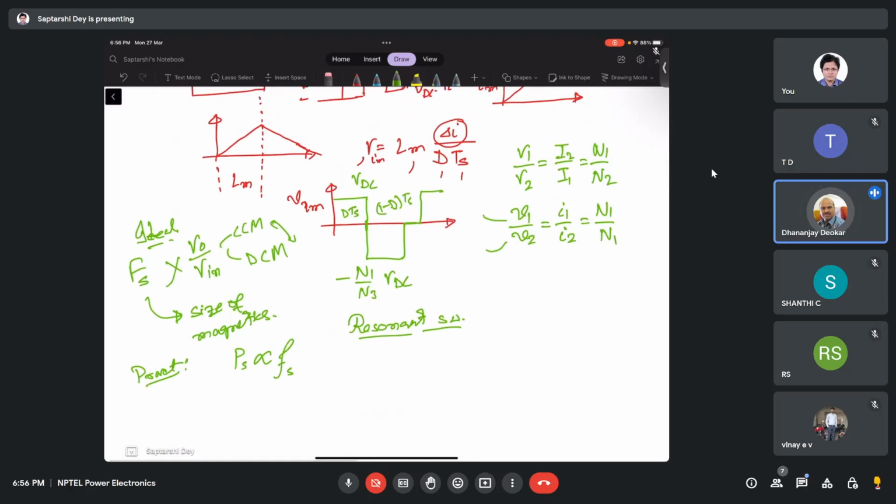In a DCM, the transfer ratio is not going to be the same, because the quantity of FS and the load are also going to matter. Unless there is a switch between CCM and DCM, in CCM it will not matter, but in DCM it will. If it does not switch between CCM and DCM, then in CCM the relation does not matter. For DCM, the relation changes. The ratio or gain, whatever you get numerically, that changes.